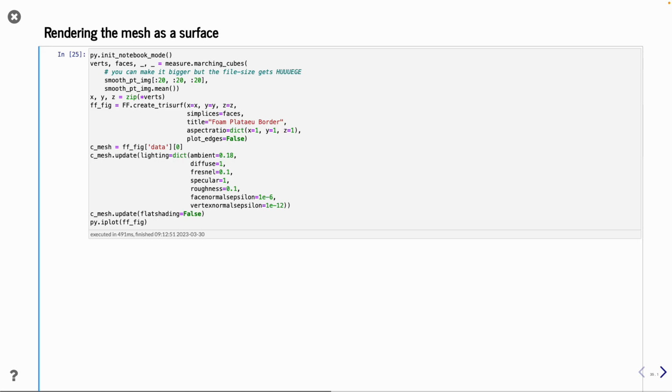And I think I have skipped some slides here because the idea was I should talk about Marching Cubes here, which is an algorithm that can identify where you have the surface. The algorithm goes through the image, looking at the neighborhood for different constellations of black and white, and from that it can get the nodes, the edges and the vertices from triangles that describe the surface.